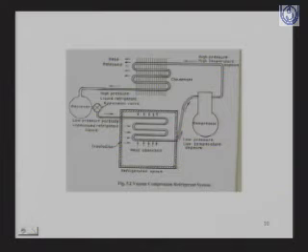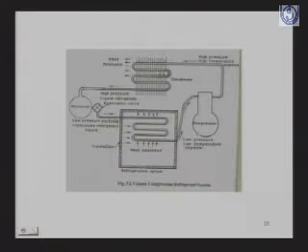This is showing it in a more diagrammatic way. This is the compressor. This is the way we show the compressor. From the compressor, the vapors move to the condenser. The high pressure vapors are condensed, and in the condenser they change into liquid.